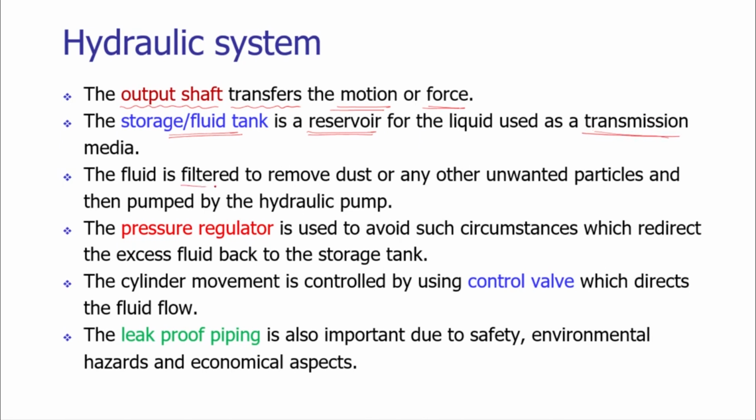We need to filter out the dust or the unwanted particles that may be pumped inside the system. We need a pressure regulator to avoid circumstances in which there may be a failure of the system due to excess pressure.